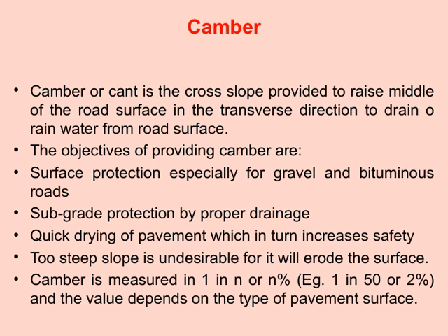By ensuring water drains off efficiently, we reduce the risk of surface deterioration. Second, camber also protects the subgrade beneath the pavement by promoting proper drainage, which keeps the foundation solid and stable. Another critical point is safety. When water dries quickly from the pavement, it reduces the risk of skidding and accidents, especially during rainy weather. So, a well-designed camber contributes directly to safer driving conditions.